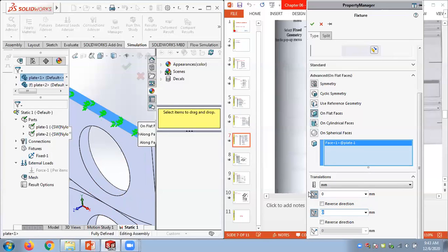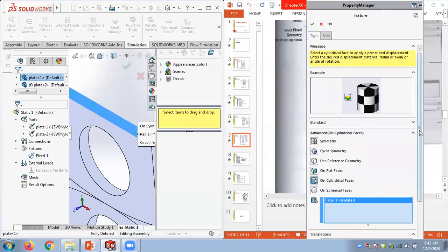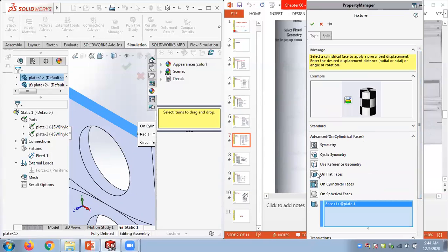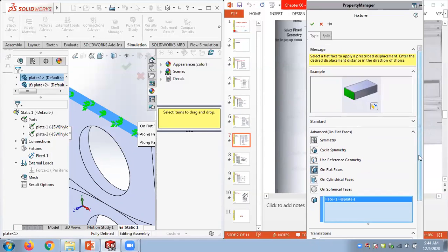Last time also, I think first week or second week, we discussed this on flat condition. Same thing can be given for cylindrical surfaces. So if you want, you can allow motions in radial direction, or after applying the load you can ask this to be rotated, or you can have it axially moved. Likewise, this case also was discussed last week. So remember these kind of restraint conditions.